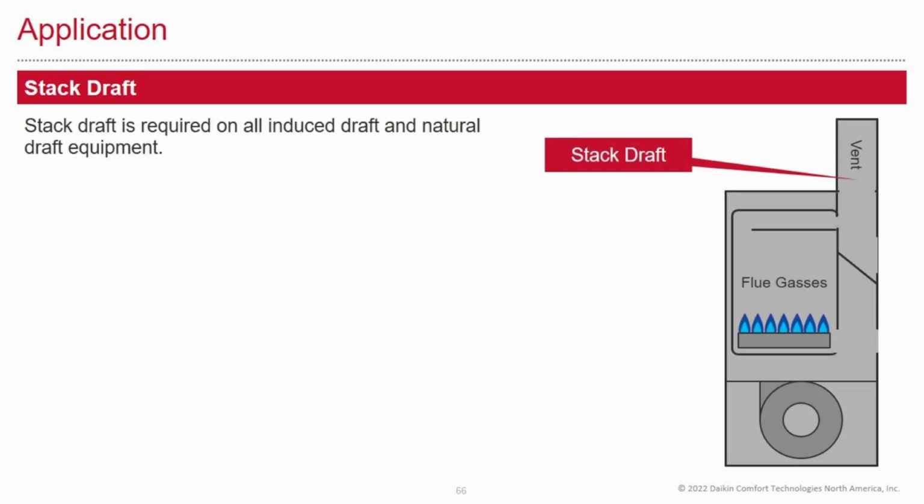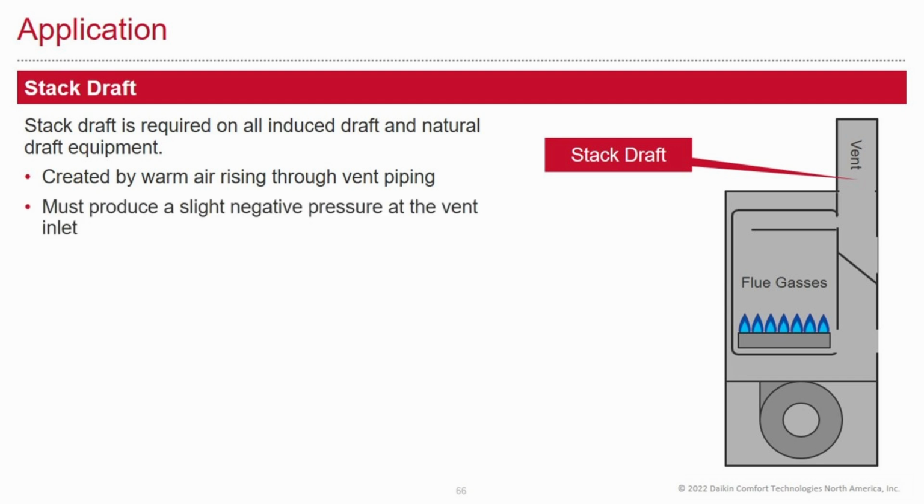Stack draft. Stack draft is required on all induced draft and natural draft equipment. It's created by warm air rising through the vent piping. It must produce a slight negative pressure at the vent inlet. It's used to carry flue gases out of the structure.